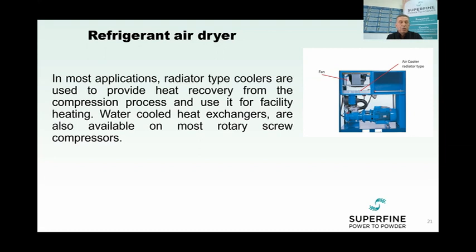They fall into two categories, cycling and non-cycling. As the name implies, one type runs intermittently and the other runs continuously. Users should consider cycling dryers, which only power up to meet demand and thus reduce electricity consumption and energy cost.